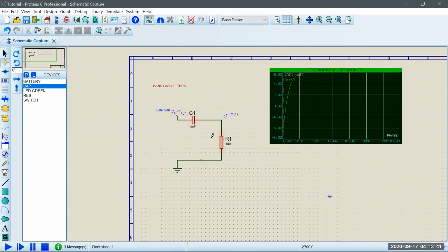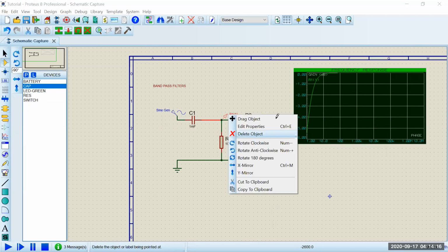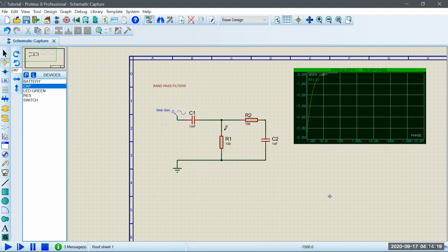Then we're going to attach a low pass filter here. To create a low pass, we need a resistor there, and then we will have the capacitor. We have it there. Okay, then we connect this, then we connect this one to the ground, and the one that we're going to probe is no longer here, but on this side.